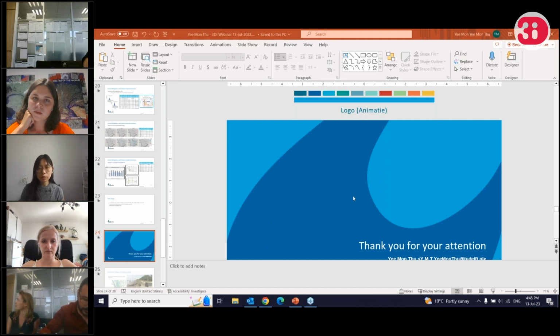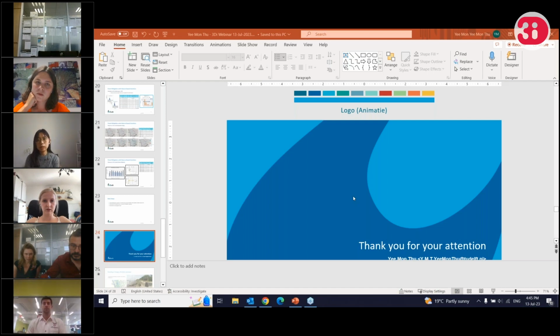I'm currently using type 4, because I would like to consider the same thickness for the interflow layer. My consideration is that the impermeable layer has the same thickness as the porosity layer and the interflow layer, and I would like to consider the lowest level of the cell in each calculation for the whole domain. So I'm currently using the type 4 interflow layer calculation.